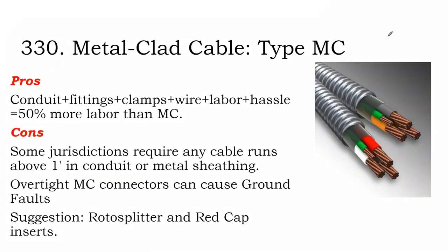And so generally with this MC cable, here's the house. If you're putting your inverter on the north side of the building and the solar array is on the south side of the building, here's your solar array up on the rooftop. I put a specialized metal box right up here on the rooftop, and then I run MC cable through the box, strap it through the attic, and then out the other side.